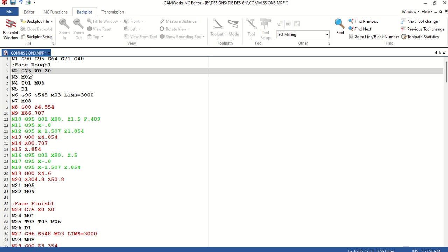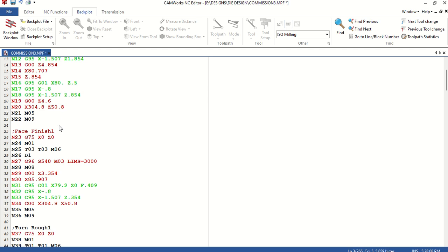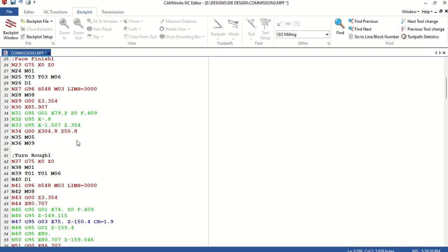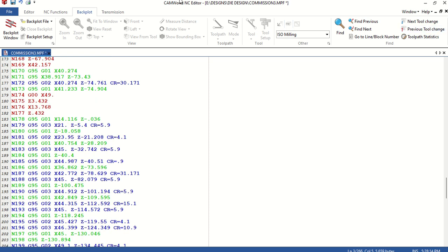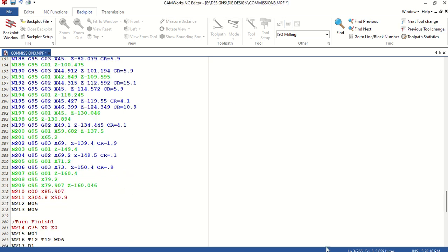But Siemens has a different language for the advanced controllers from Siemens, 828D, 840. It has this G75, which you can also convert from this Siemens language to ISO language. You see the program is advanced. That is how programs are. So you can use different programs.